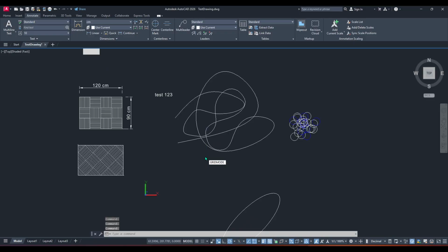If you prefer keyboard shortcuts, there's an even faster toggle. Press the F7 key to switch the grid off or on instantly. This is especially handy when you want to temporarily hide the grid for a cleaner view and bring it back later. On some laptops or on macOS, you may need to hold the Fn key while pressing F7, depending on your keyboard settings. If nothing seems to happen, check whether your function keys are set to media controls and adjust as needed.